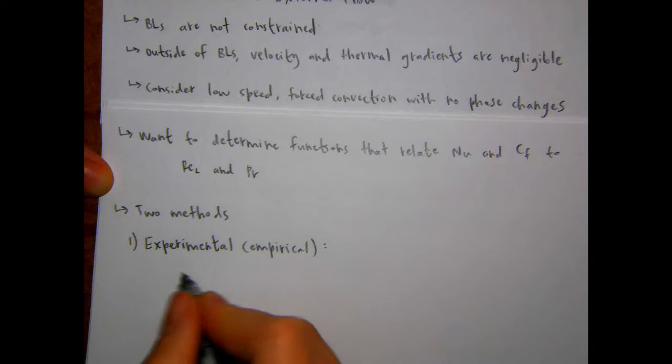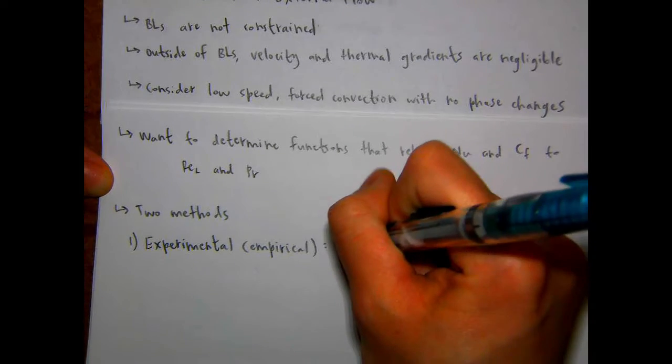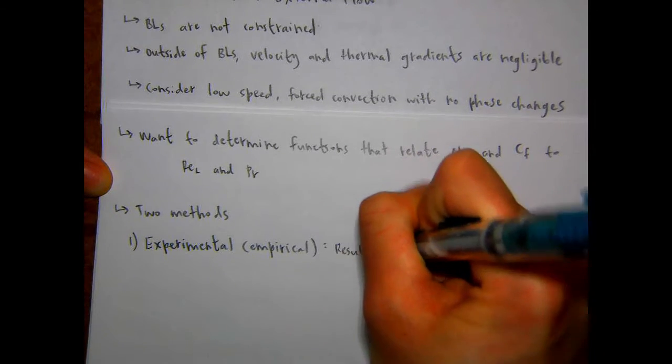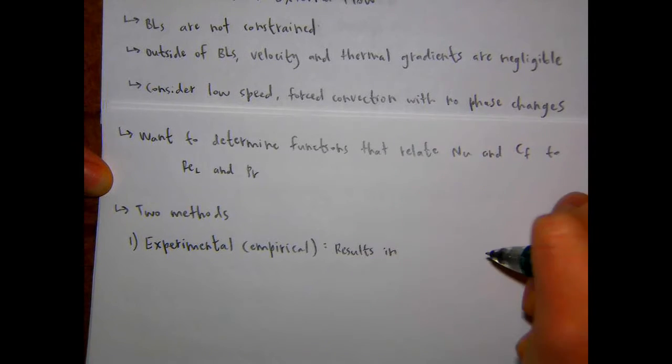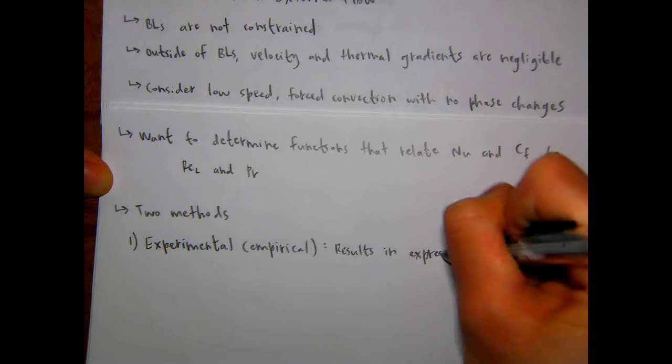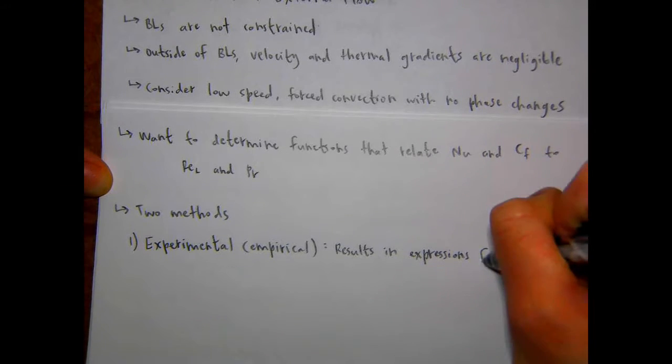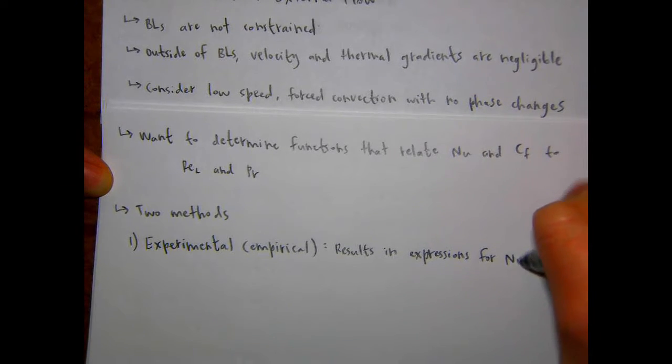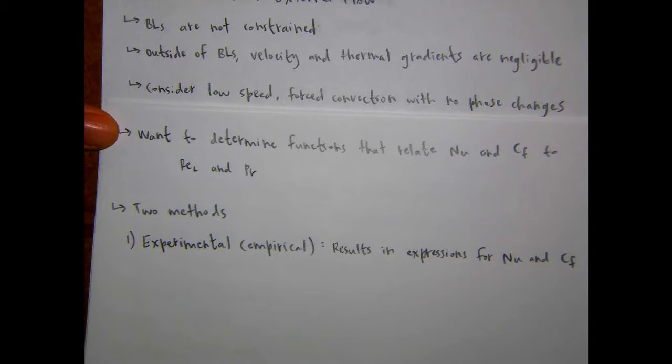So let's say this basically results in expressions for the Nusselt number and the friction coefficient. And then from those, you can calculate the convection coefficient and the skin drag.